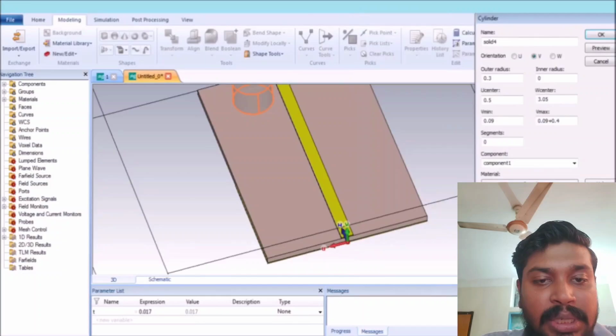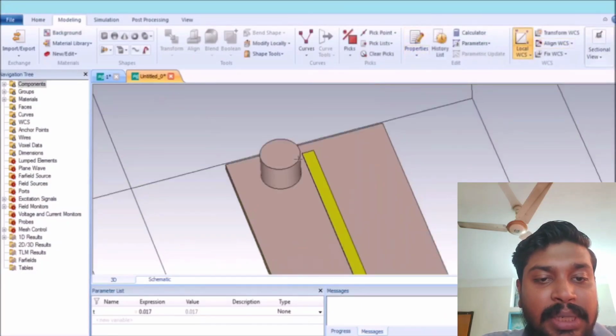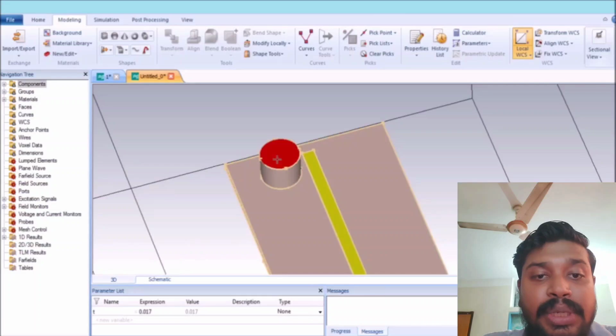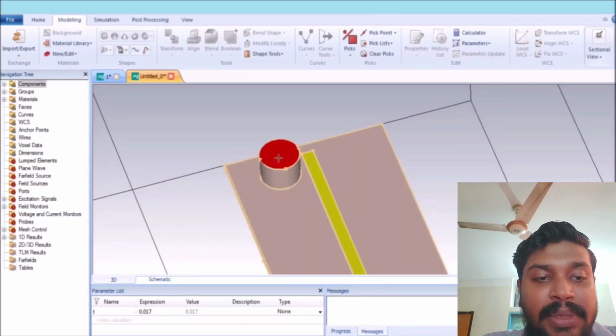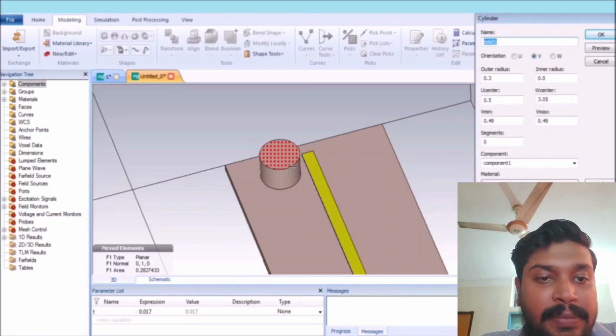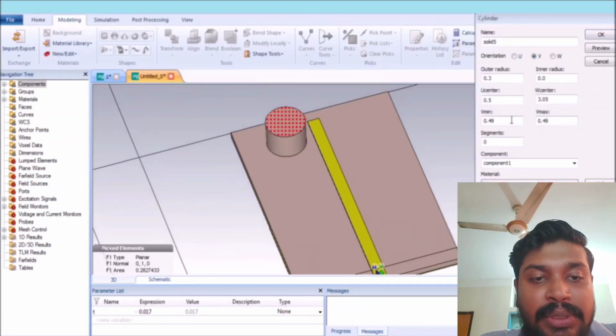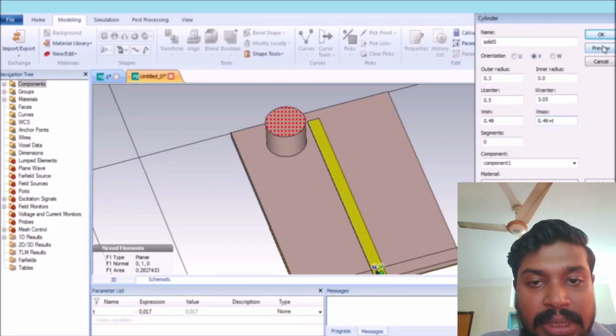and I'm going to select the surface by pressing S, double click on it. I want to put a copper patch element on the top of it, so for the copper, I'm gonna go to the coordinates, thickness is equal to the copper, which is considered as T, and the material is copper.